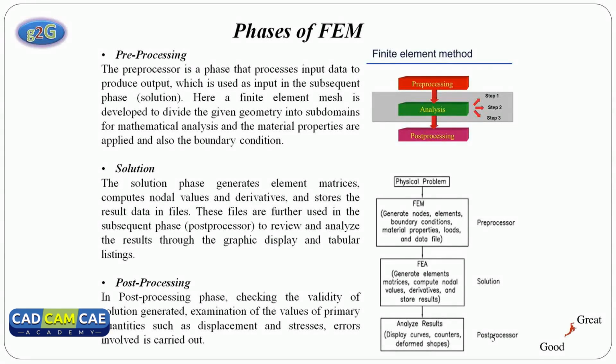The next is the post-processing. In the post-processing phase, there will be an interpretation of results in the form of contour plots. So in the post-processing, we will be finding out the output parameters like displacement, stresses, strains, and comparing them with any other method.